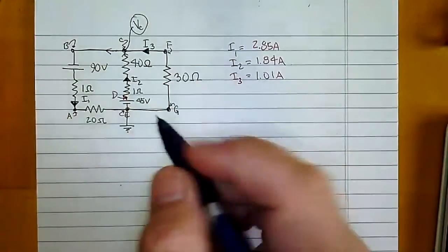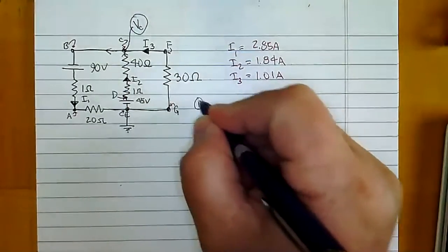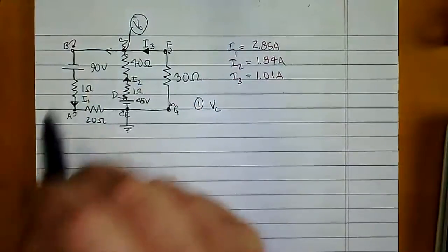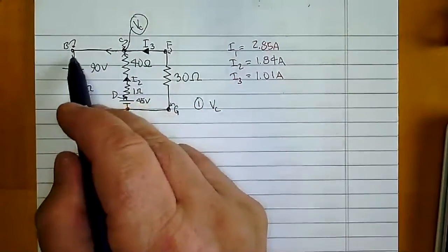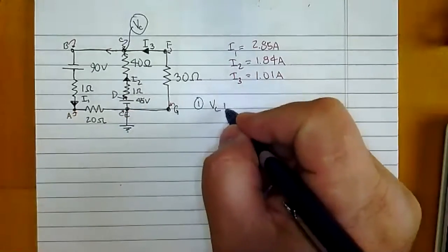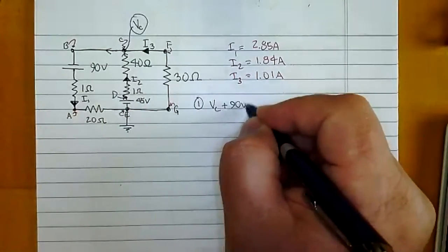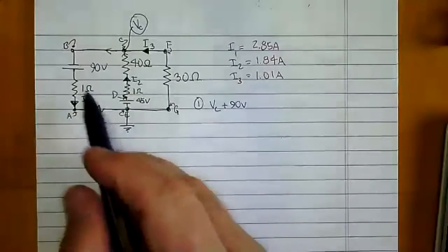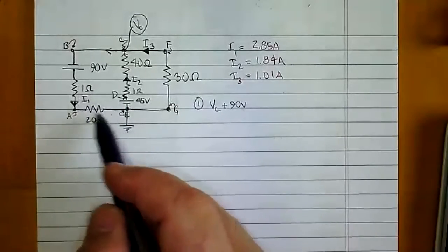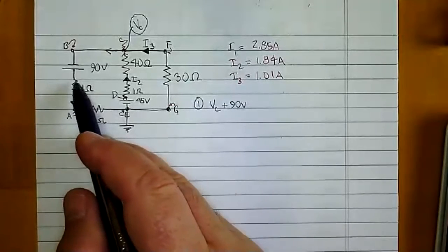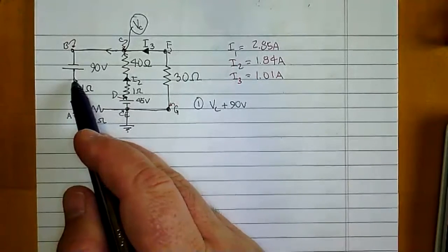And you say, all right, here's equation one. The voltage VC is what you have there. But then as you go this way, I go from a negative terminal to a positive terminal of a battery. So that means my voltage increases by 90 volts. And I'll drop these volts and ohms and stuff later. And then since I'm going in the direction of the current, I1 goes this way in my diagram, I know it's going to decrease.